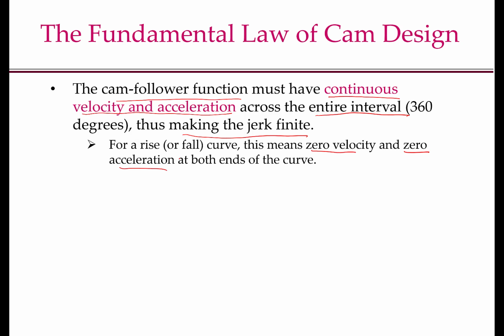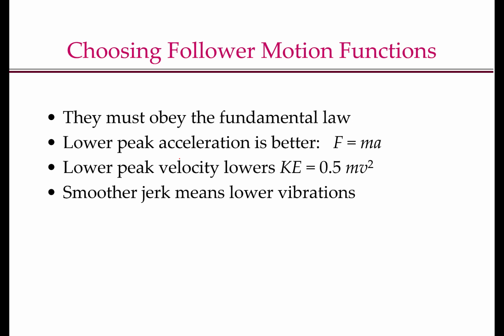This is the most important fact that you have to remember for designing follower motions of cams. And this is what we will be using throughout the rest of this module and the next module. Apart from the fact that the cam follower motion should obey the fundamental law, there are 3 other desirable characteristics of the follower motion. First is that lower peak accelerations are preferred. Second, lower peak velocities are preferred. And third, smoother jerks are preferred.